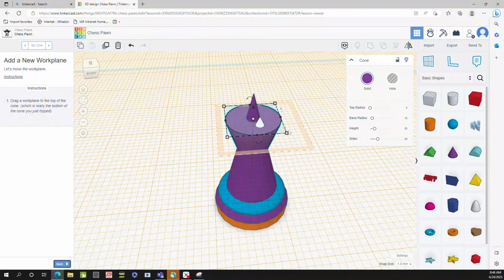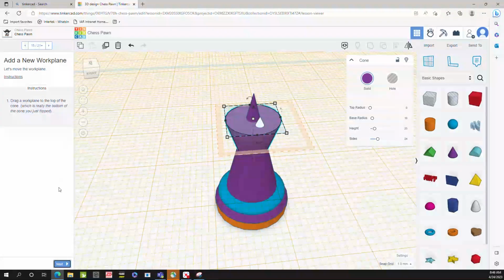And that's important because later, when you want to do finite element analysis, all those figures should have some positive plane direction. So the objects that we have are the cylinder, this cone, this sphere that now has a funny shape. All those objects need to have the same direction on a plane. If not, when you create your discretization in your mesh or your grid, you're probably going to have some issues. Okay, but we're not doing that.